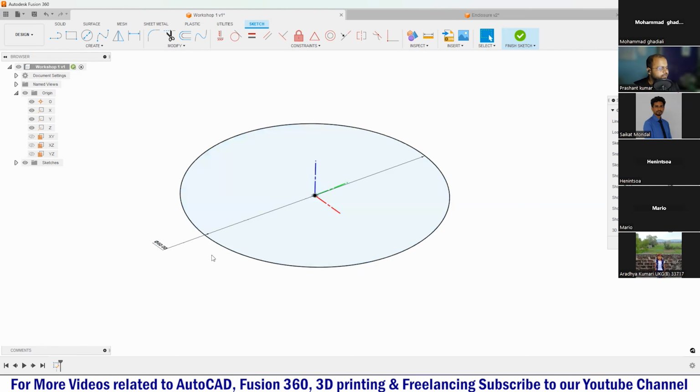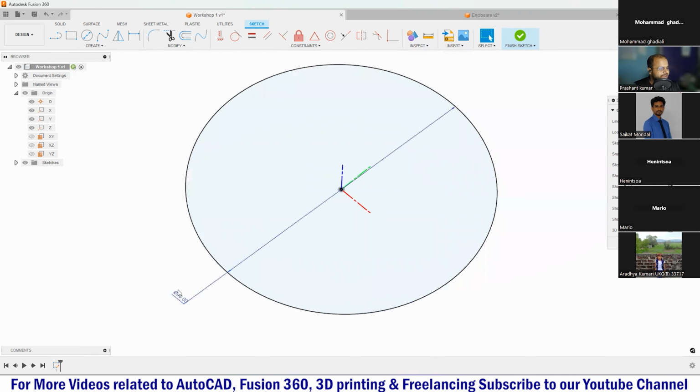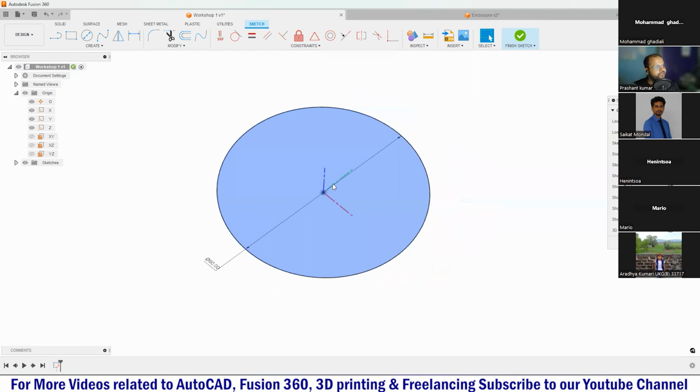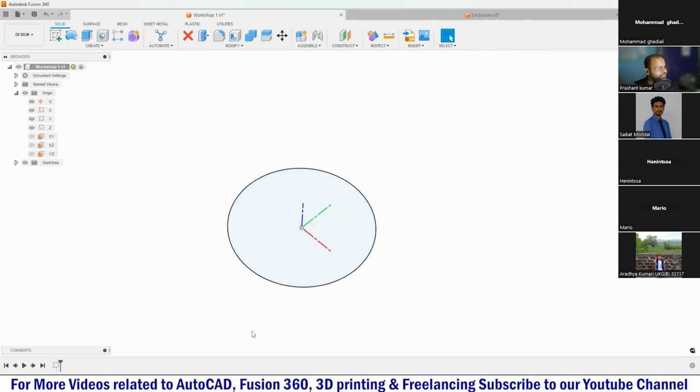So here you can see we had just created a circle of diameter 60 millimeters, and phi is the symbol for diameter. This means it is the diameter. Now, the moment I am done with sketching, let's say I had to create only this circle sketch, and the moment I am done, I can just click on this finish sketch tool over here. I will just click on the finish sketch tool, and here you can see the tool just finished.